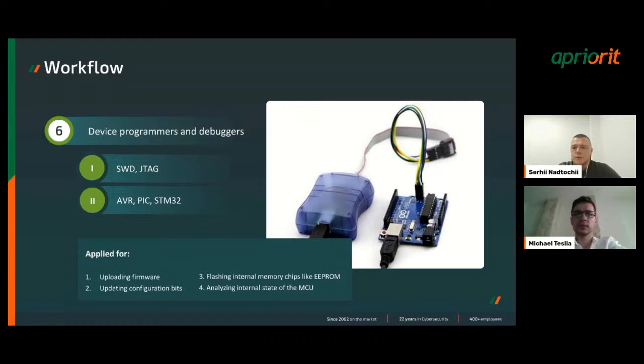So yeah, it will be very useful, but you probably need to have several of these devices because each manufacturer develops its own ecosystem. So you cannot, for example, take an AVR programmer and connect it to an STM32 microcontroller. They will not be compatible, and you may need several tools for dealing with this task.